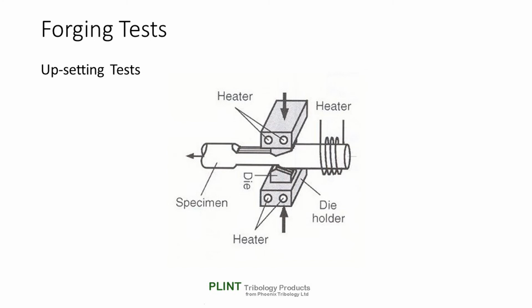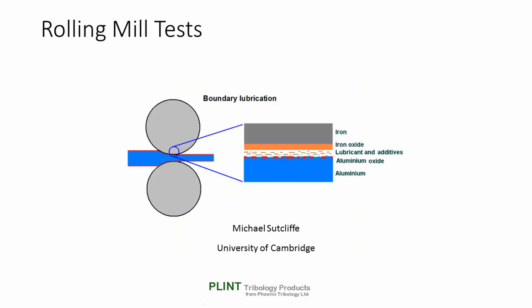In most cold rolling operations, lubricant is used to reduce friction forces, to protect the roll and strip surfaces, and to act as a coolant. The amount of oil drawn into the roll bite and the initial surface roughness are the critical factors determining friction in the contact and surface finish of the product.